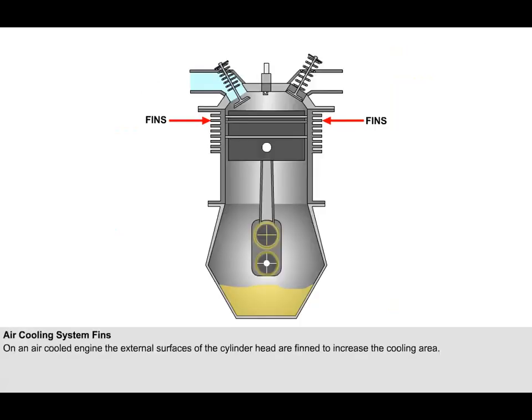The external surfaces of the air-cooled cylinder and the cylinder head are increased by the use of deep fins. The engine designer walks a fine line between ensuring that the pitch of the fins is such that a large fin area can be obtained, whilst ensuring that the fins are not too close, so that the resistance to the airflow builds up pressure, which would tend to decrease the airflow and thus increase the drag. An average pitch for fins is 2 per centimetre. The fins have a thin cross-section.